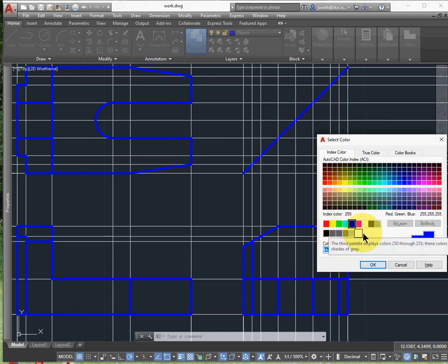Now I'm going to add a new layer called hidden, and then a new layer for center. And these are my dimension lines, so to speak. This is the center line. Make sure it's at 50 millimeters. Actually, I have it on 30 millimeters here. I actually end up changing this to 50 after this lesson because it was just a little hidden. So 50 is fine.